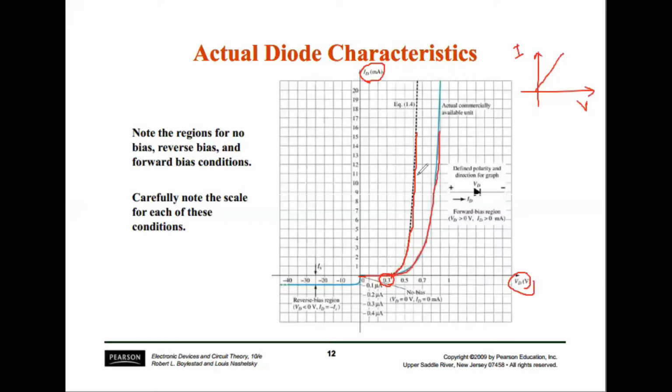These are basically two different devices. Here the threshold value is 0.3, while for this curve the threshold value is 0.5. So after 0.3, the current will increase in an exponential manner, but non-linear. That's why the diode is called a non-linear device.